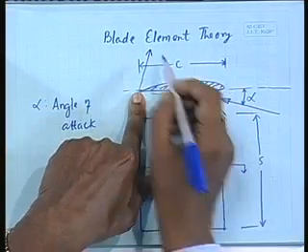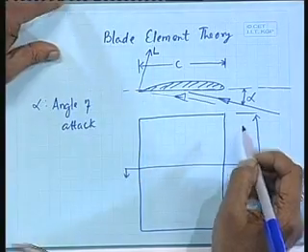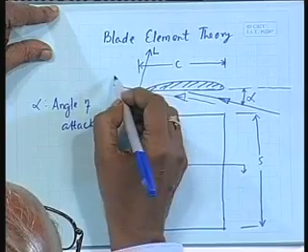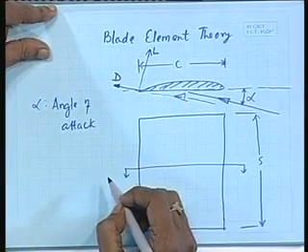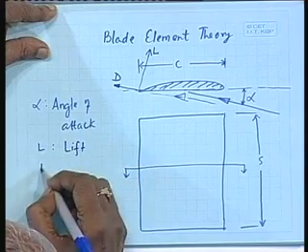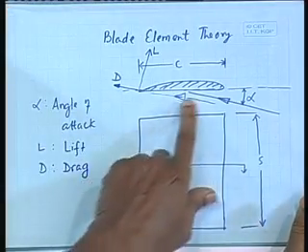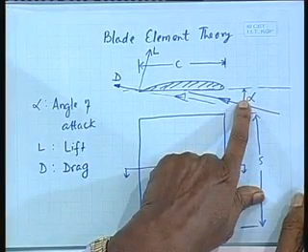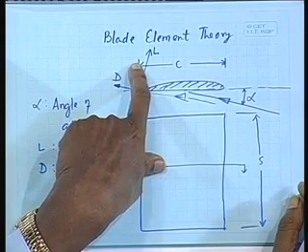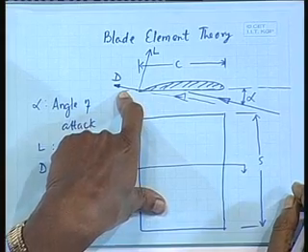Perpendicular to the direction of flow will have lift L, and in the same direction opposing the flow will be the drag D. So, L will be lift, you know this, no? So, if flow is at an angle alpha, then you will generate a lift force L perpendicular to the direction of flow and a force opposing the motion, which will be the drag force.